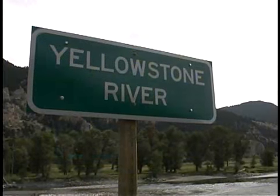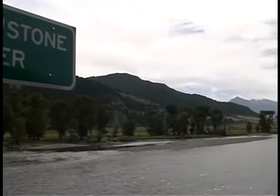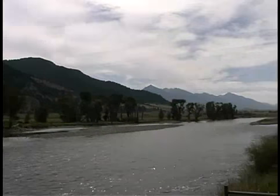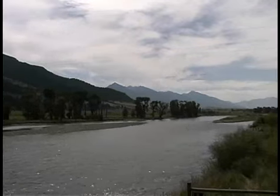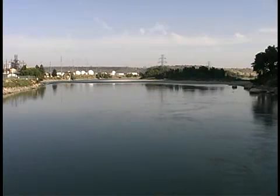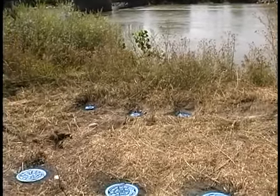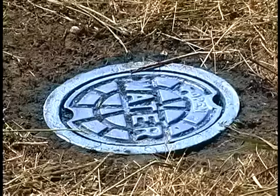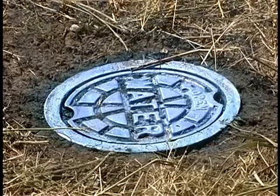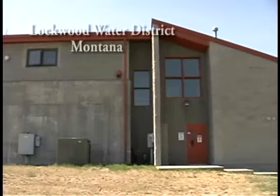Not many surface waters have elevated arsenic concentrations that are of a concern to public water supplies. However, the Yellowstone River, which originates in the volcanically active area of Yellowstone Park, is an exception. There are numerous public water systems that rely on the Yellowstone River as their source water and use coagulation filtration as their water treatment process. Two such systems are the city of Billings, Montana, and the Lockwood Water District.